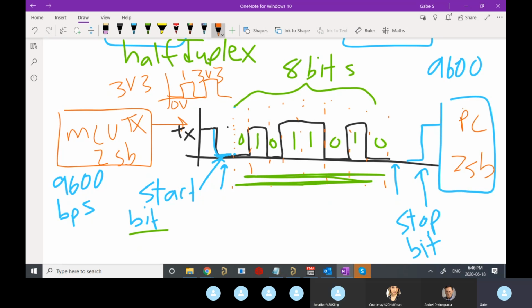Cool, thanks. Even better, how does it... I was going to ask, how does it know the difference between just a regular bit and the stop bit? Yeah, great question. That's defined on how you set up the number of bits in your data, right? After it has seen 8 bits come across, it should be expecting a stop bit at that point.